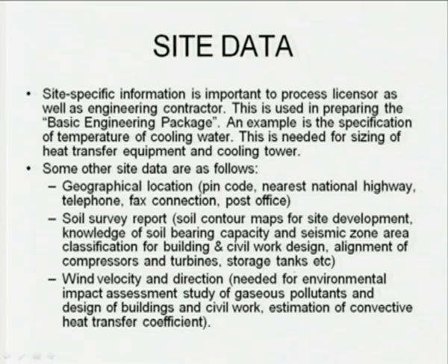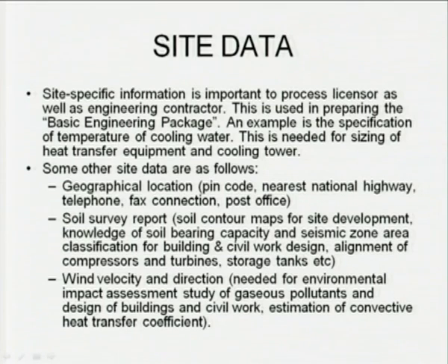Then alignment of the compressors and turbines, then the location of proper storage tanks, their capacity. And again this requires the soil survey report. For storage tanks, the volume will be high, and so will the total weight of the storage tank. So, the soil bearing capacity should be high at the site at which you would like to build the storage tanks.